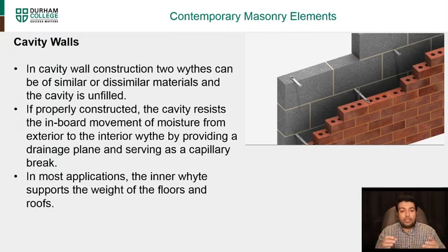In most applications, the inner wall supports the weight of the floor. So basically, the one inside is the structural wall. So for example, in this case here, you can see that the solid masonry block in the back is probably the structural wall, and you have these ties that are connected to the brick on the outside.